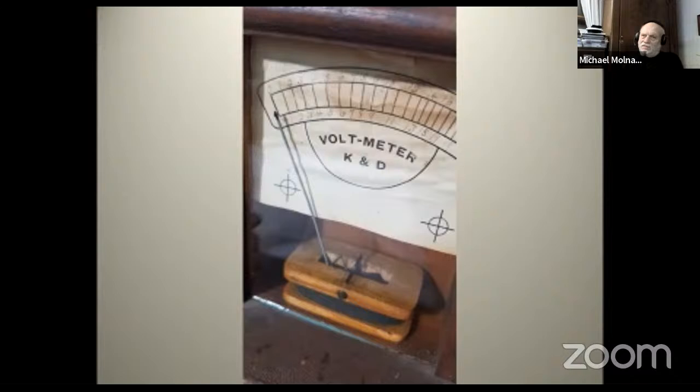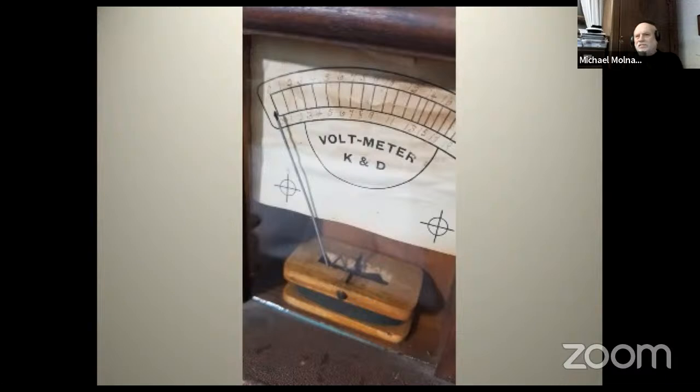To act as a voltmeter, the voltage is applied to a positive terminal and into the coil, then exits the coil and into a fixed resistance, then to the minus terminal. When a voltage is applied to the coil, it produces a magnetic field strong enough to overcome the force of gravity and deflects the magnet and indicator in a way that's proportional to the voltage that was applied.